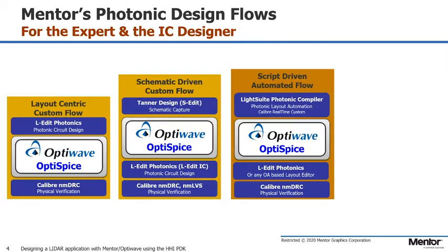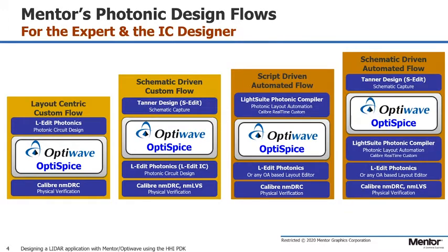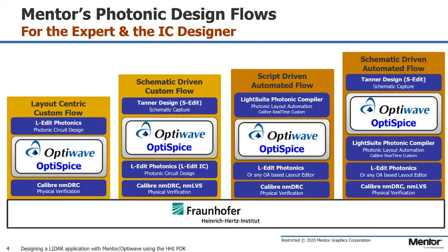We also support the schematic-driven approach with our LightSuite Photonic Compiler. So again, you start with your schematic, you drive your circuit in OptiSPICE, verify the circuit is working correctly, then drive LightSuite Photonic Compiler to do all the automation and scripting. And then final chip assembly again in LEdit Photonics with Calibre, DRC, and LVS. All these flows are built on top of the HHI PDK.